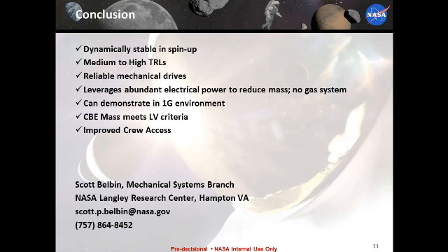We're looking at medium to high TRL on technologies. These are drive systems that already exist and have been used for many, many years in deploying solar arrays, just as the ATK gentleman has said. We're using the electrical system and not a gas system, so we're not carrying the extra mass of a gas system. We can demonstrate in a 1G environment, similar to what Brian has said with their concept. You'd put it in a vertical configuration, and because we're not inflating, we don't necessarily need to be in a vacuum chamber, just still air.